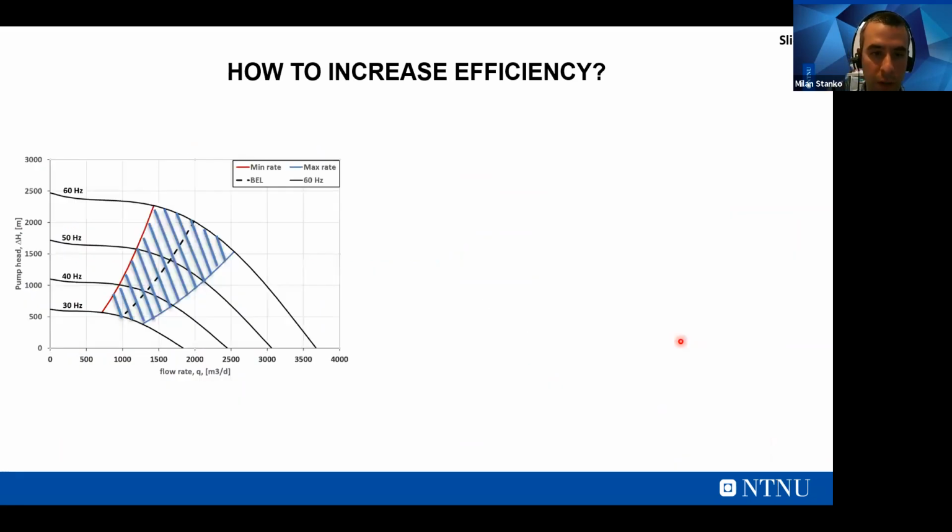operate your field. Another thing we did was to look at the feasible operating region. Remember, it has to be modified by viscosity. But especially these days, you're very interested in energy usage. You want to reduce the usage of energy. So the intention was, what happens if we operate close to this line, which is the best efficiency line?